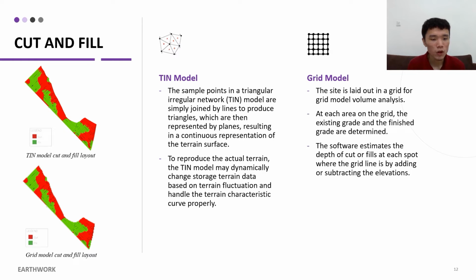The procedure to construct TIN model are as follows. First, select a data point A near the geometric center point of the area containing all the original data points. Then find the data point B closest to point A and connect A and B to form an initial baseline. Then use the empty circumscribed circle criterion to find the data point C that satisfies the condition as the third point. The 3 points A, B, and C form the initial triangle.